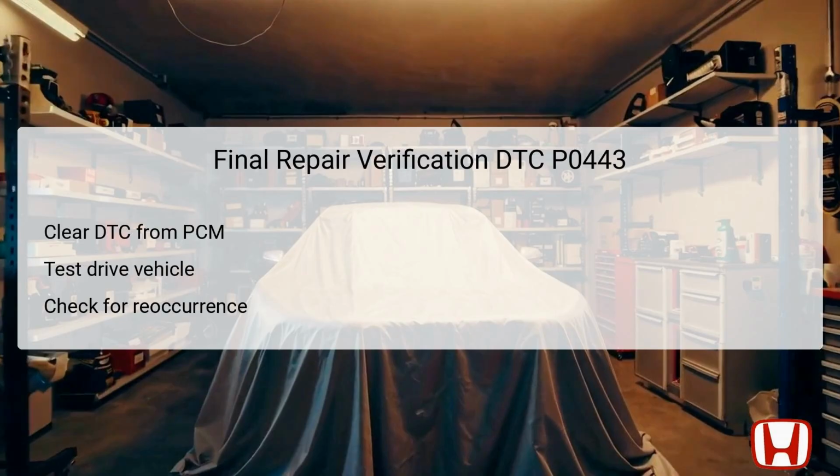Once repairs or replacements have been made, it is crucial to verify the effectiveness of the intervention. Start by clearing the DTC from the PCM using a scan tool, which resets the diagnostic trouble code memory. Following this, a test drive should be performed under various driving conditions to allow the vehicle to run through several cycles of operation. This ensures that the EVAP system and any associated components function correctly.